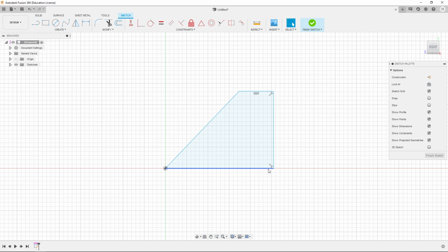This angled T is a perpendicular constraint. And if we look at the menu, here it is, perpendicular. And hopefully you know from your math, perpendicular means that the lines are 90 degrees rotated from one another. So this is a horizontal line, so 90 degrees downward would be a vertical line pointing down. Similarly, this line is a vertical line, and the perpendicular line is horizontal to the left. So these are perpendicular constraints. These were done automatically because I made lines that were pretty straight. But if I didn't, I could force them by using the constraint tool. Sometimes it's automatic, sometimes we'll choose our constraints manually. Another constraint that happened automatically, and we can see the little icon here, is called the horizontal constraint.